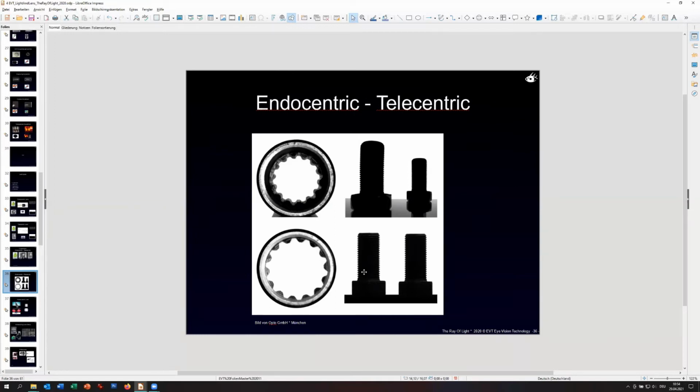It's exactly the same height, so you don't have to think or correct. Of course, in this case, you could calibrate the field of view on the back and on the front, and you can measure it anyway. But if you cannot calibrate, or you don't know where it is, at the end, it's much easier to simply use a telecentric lens.